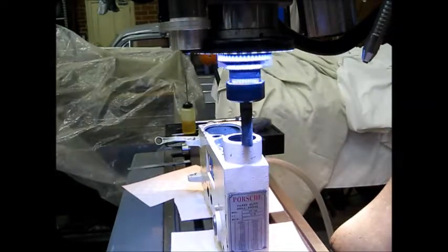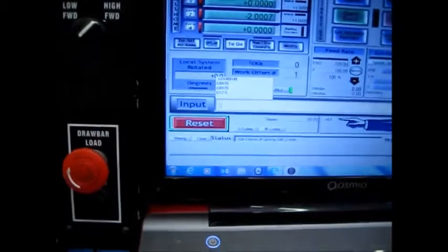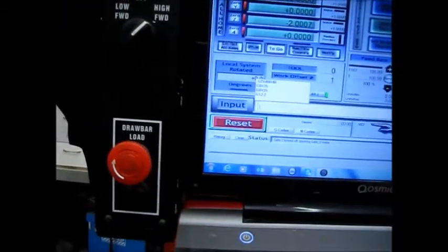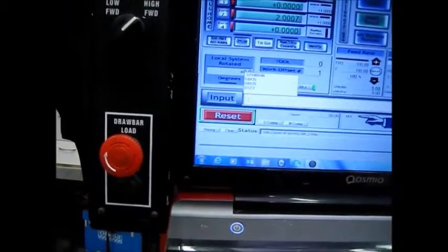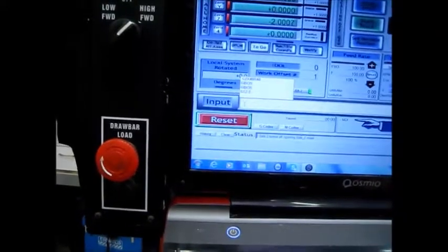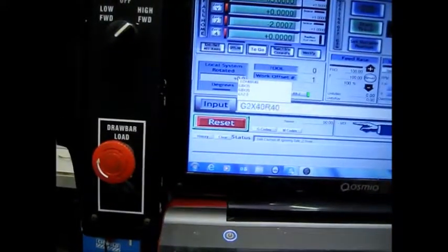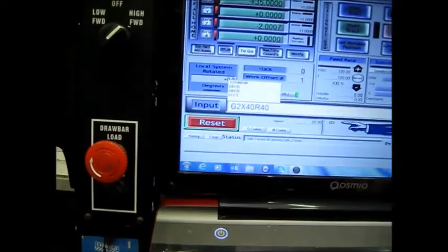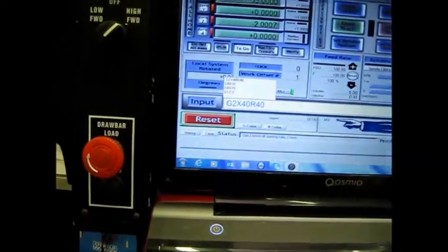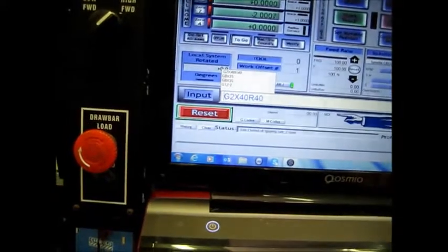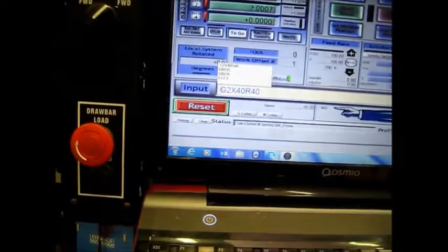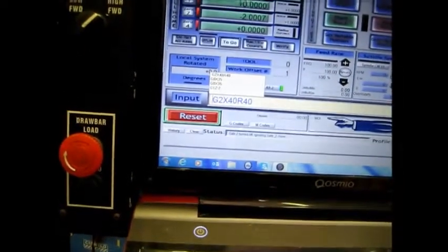So the instruction for a G code to turn a radius is something like this one I've got here. We're currently at plus 35. I'll move up using the up arrow key here to this instruction. We've got to go G2, which is to cut clockwise around that boss.